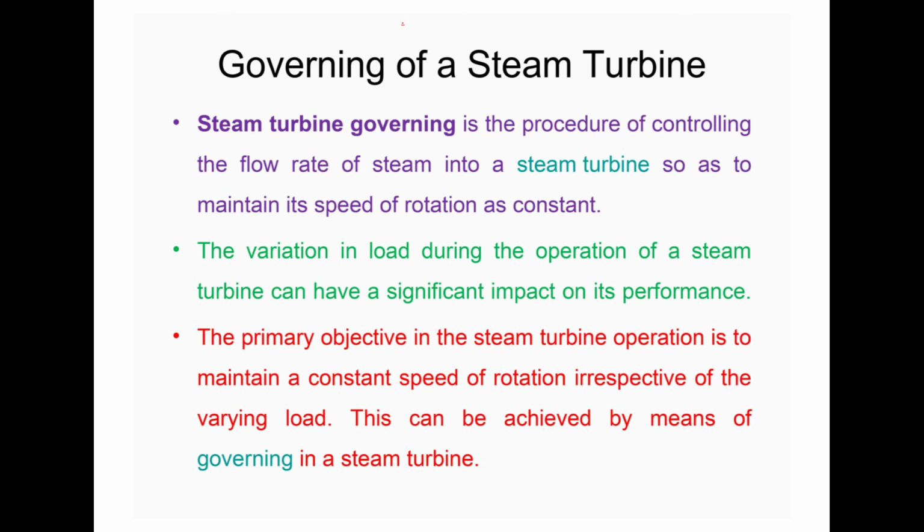This looks like a governor in the automotive industry. When the steam supply exceeds the required level, the governor automatically brings down the steam opening of the nozzle, so that high pressurized steam cannot enter the turbine section. Because of that, we can reduce the steam to control the turbine speed.